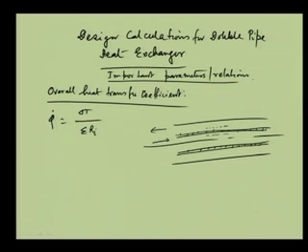There are 3 resistances possible: the inside film of the inner tube, the outside film of the inner tube, and the resistance due to the thickness of the tube.